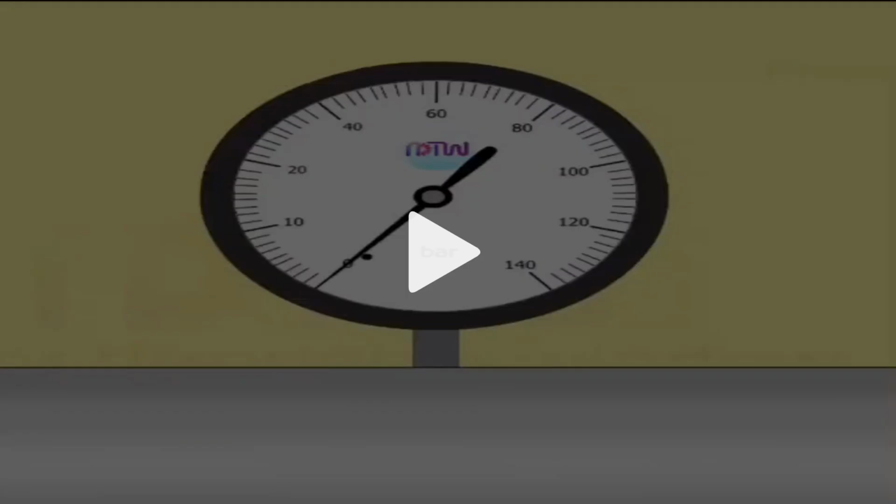And when pressure enters into the Bourdon gauge, you can see here the pressure enters into the Bourdon tube and the tube is bending slightly. This movement is transmitted through the mechanical linkage and the gears. And now the pointer moves over the calibrated scale to indicate the pressure value. So this is the practical example of how a measurement system converts a physical quantity to readable information.